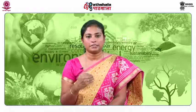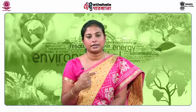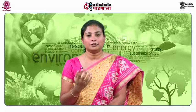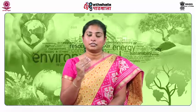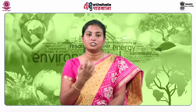Now, the next parameter is temperature. You should continuously monitor the temperature within the landfill bioreactor because it will indicate the stage of biological activity within the bioreactor. Temperature monitoring is very essential, especially for aerobic landfill bioreactors, to avoid fires, because sometimes the waste can catch fire.